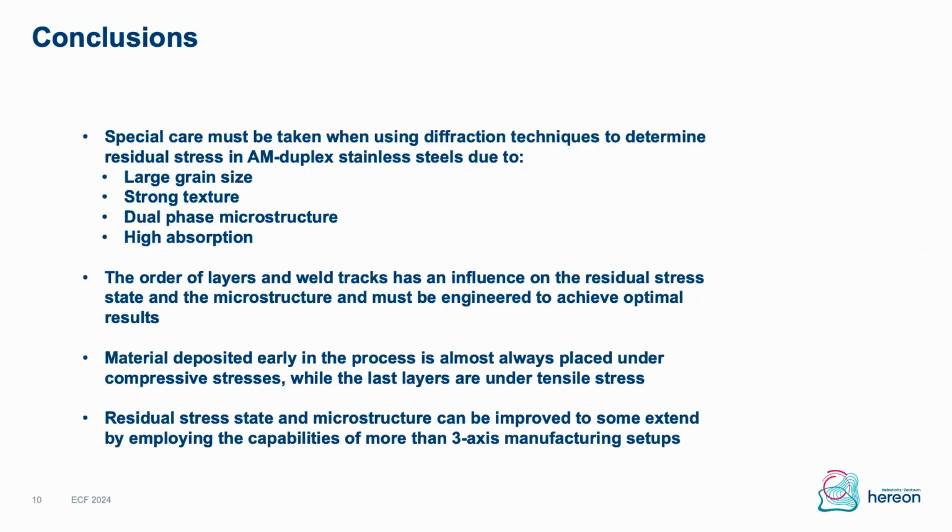So in conclusion, we learned a lot about the evaluation of stresses in duplex stainless steel using synchrotron radiation, which is very difficult to do due to the large grain size of the prior ferrite grains, strong texture, the dual phase microstructure, and because we have high absorption from the high wall thickness. We learned that the order of layers and weld tracks has an influence on the residual stress state and the microstructure, and they must be engineered to achieve optimal results.